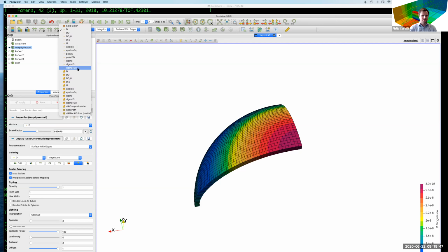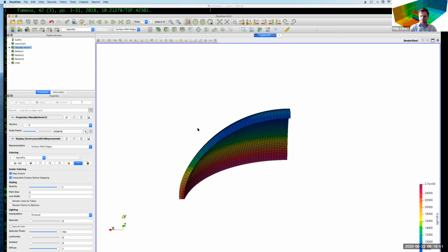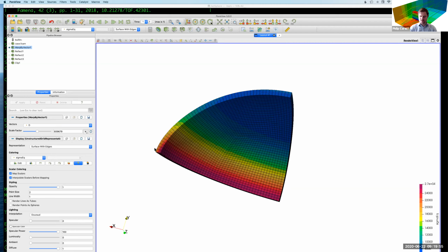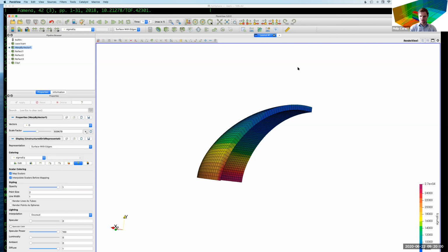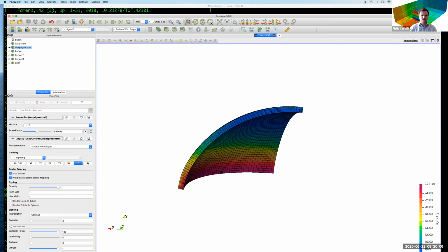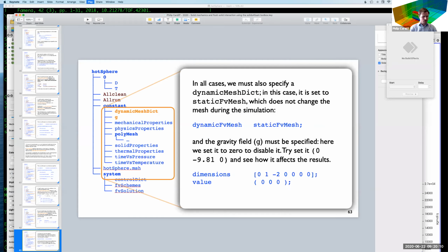And you can look at all your stresses and things like that. So in this case, the maximum von Mises stress is on the inside here. So if this was half a pipe and it was flat and was getting squashed under its own weight, you would expect the inside here maybe would start to permanently deform first or break first.